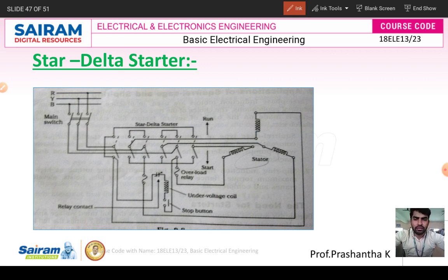So why we need a starter? To start the induction motor, to limit the starting current, to limit over voltage, and so on. That purpose we are using the starter. So if it is run condition, it becomes delta if the rotor speed reaches 80%. If the rotor reaches 80%, the starter is not required, so we can eliminate that starter, because back EMF is present, back EMF is developed in the rotor. So that's why we need a starter, okay. And also the main purpose is limiting the starting current. Keep it in your mind, okay.